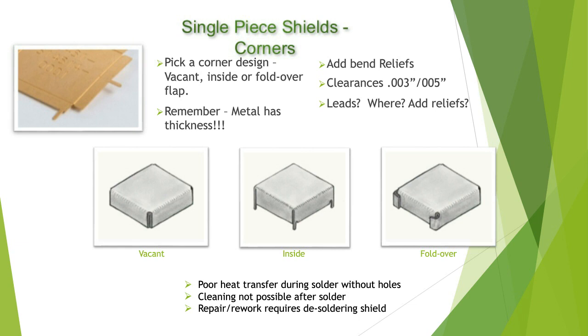If you're going to have to clean your board after you put your shield on it, you're going to have to provide holes for that as well. This can be accommodated through holes in the top, or mouse holes as we call them at the bottom. I'm going to talk about mouse holes later. That's something else you've got to think about.